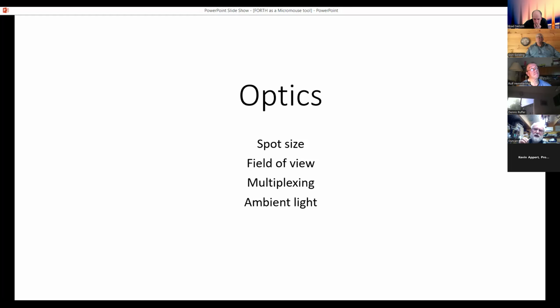You need to consider any direct optical path between the light source and the sensor. So the light source and the sensor might be pointing in the same direction, but there might be light flowing directly across between them, and that will affect you. So I sometimes use Tipp-Ex or black paint or bits of cardboard or anything like that to block this direct path. And you also need to think whether the sensor is shielded as far as possible from ambient light. So for all those reasons, blinds, mirrors and lenses have all been used. Don't imagine that sensors are easy to design.